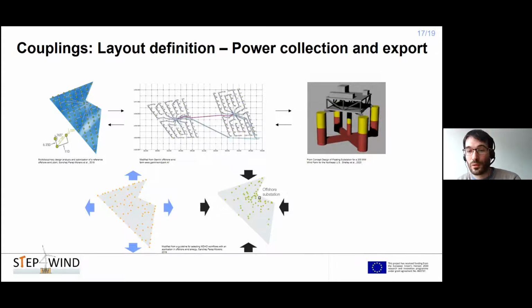In the picture below, you can see what would ideally happen if a designer wanted to maximize only energy production in a farm. We would obtain a layout which is as wide as possible, but this will be traded with higher cable cost. If the same designer decided to minimize electrical balance of system cost, the layout of the wind farm will be clustered around the substation with turbines as close as possible to minimize electrical cable cost. But this will cause a lower energy production in the end due to wake and dust losses. So, another trade-off.